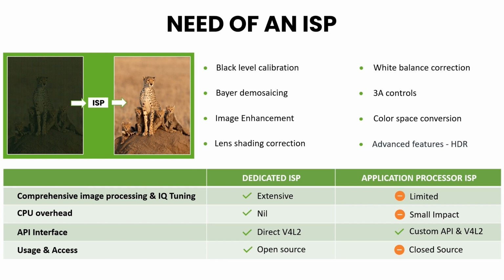serializer deserializer input. Cameras using these interfaces can support an API called V4L2, also called Video for Linux 2, which is part of the Linux OS and has been a standard for embedded vision cameras since 2002. There is a huge community of developers who have been using V4L2 to talk to cameras since then. Even the most popular computer vision library, OpenCV, supports it.